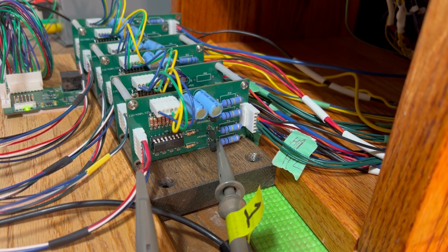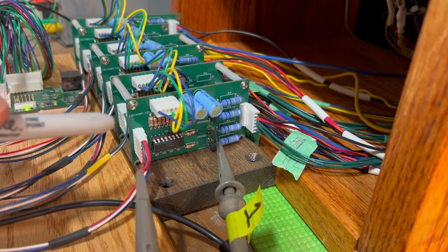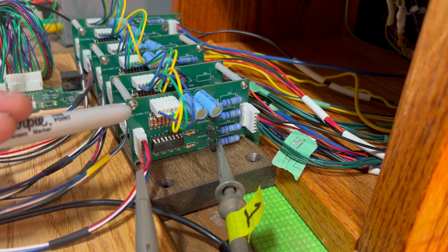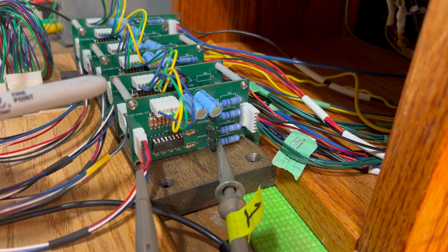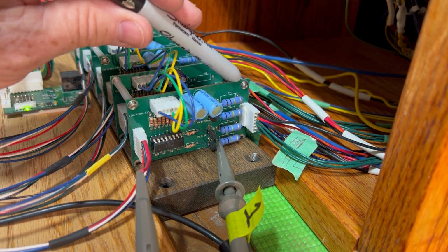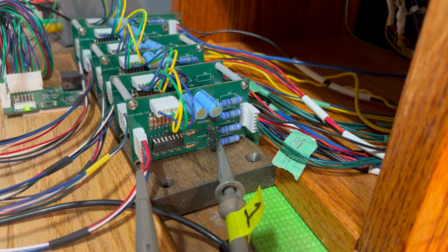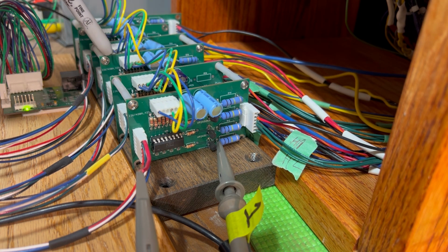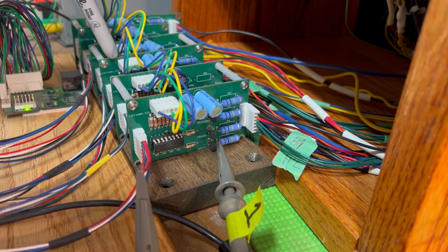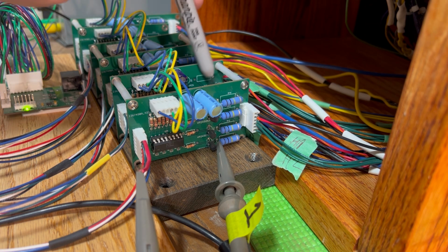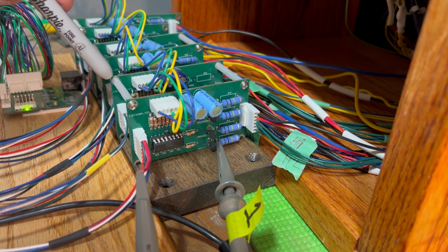Let's have a look at the selector bar driver boards. Each card that we see here, each one has 4 drivers on it, so I grouped them sort of naturally with the way the tube presents itself. So this first grouping of 4 is the H group, H1, 2, 3, and 4. I'll go to the back. These 2 are for the H prime group, H prime 1 through 8. This is the V group, V1, 2, 3, and 4. And then finally, this card right here, which is only half populated, is the V prime group, V prime 1 and 2.